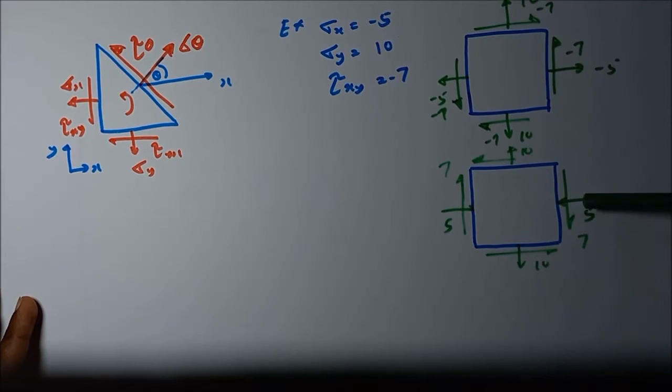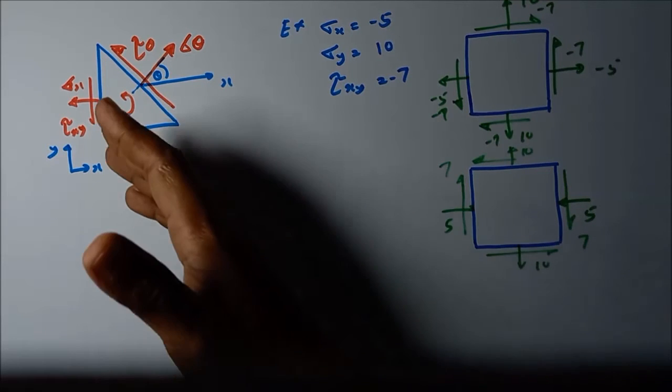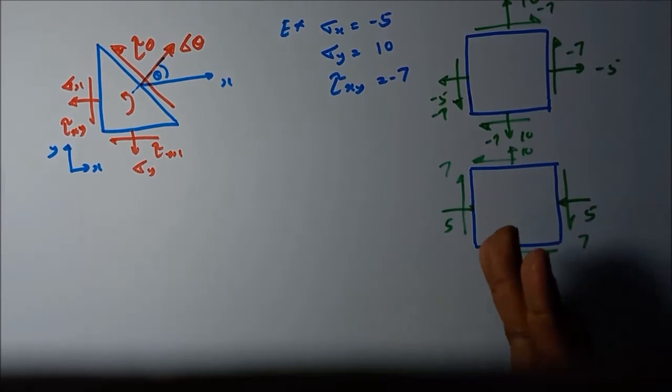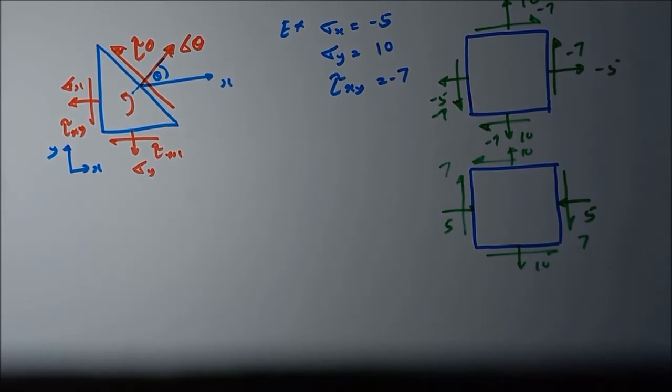Here also we changed the direction, it is acting inward on the stress element. Those are negative values, so there is no need to put the negative sign, because we have already represented it as a negative stress. This is how we mark the shearing stress and normal stress acting on normal planes and also inclined planes in a biaxial stress system. I think you all now have a clear idea how to mark these stresses on a biaxial stress element.